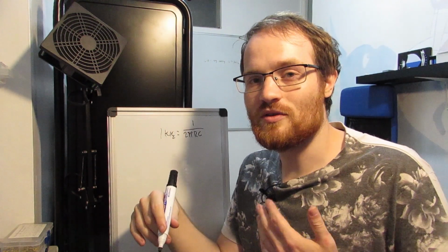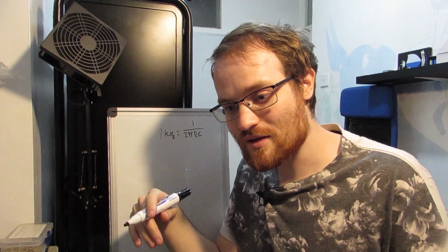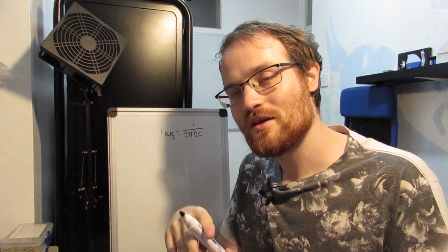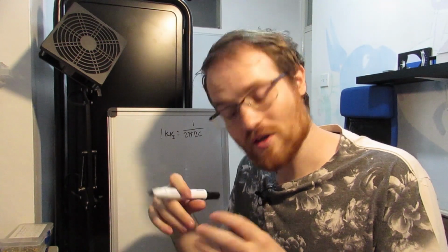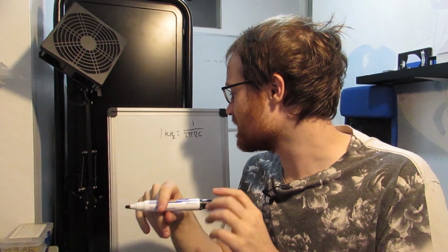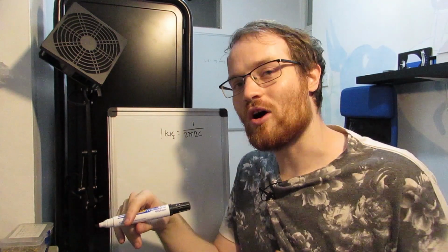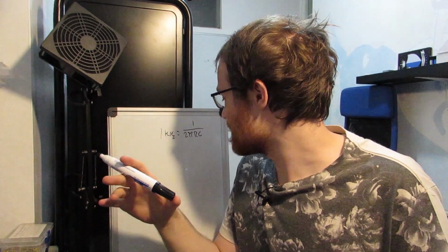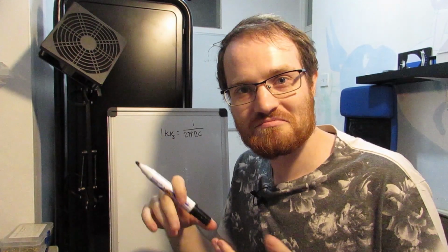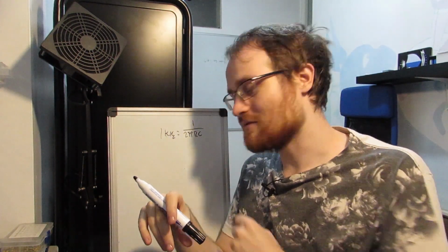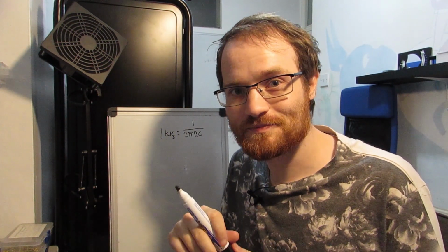Generally, you want to think about the impedance, the input and the output impedance of your little circuit block and how that's going to interact with the rest of the circuit, which we will go on to in a minute if you don't know what I'm talking about. So for now, we will just pick a 0.1 microfarad capacitor, just because that's a nice round number, and we'll calculate the resistor number and we'll see what comes out.